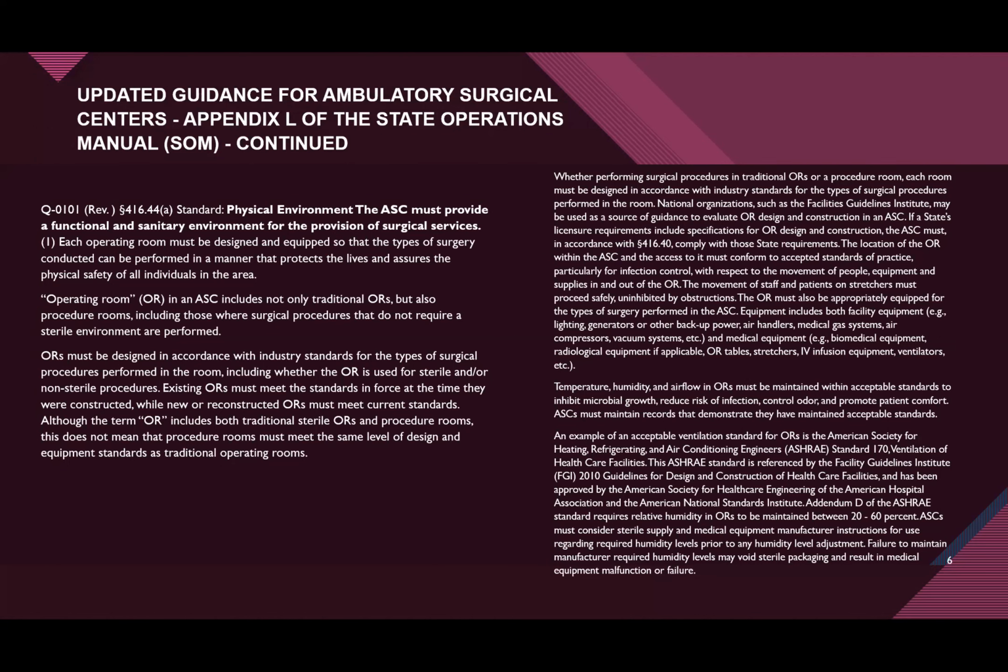The biggest challenge I have seen recently with humidity is that CMS has stated that the ORs and sterile storage need to be maintained between 20 and 60% humidity. Prior to 2019, AAMI had said sterile supplies are good up until 70% humidity. And they deferred then back to CMS and to ASHRAE, which is the American Society for Heating, Refrigeration, and Air Conditioning Engineers. And so when you think about who's in charge, which rules supersede other rules, 70 in some locations is much easier to maintain than 20 to 60.